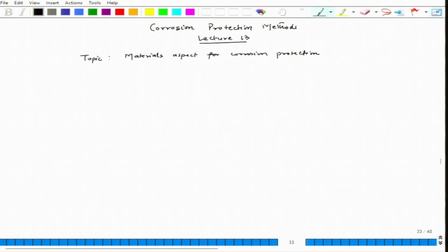One of the popular stainless steels is 304 stainless steel, used in applications like wash basins. In fact, it has more specific applications in biomaterials, where it is not 304, rather 304L, where L stands for low carbon. The carbon content is reduced from around 0.08 to 0.03 or 0.02, and we call it low carbon stainless steel. Again we have chromium about 18% and nickel about 8%, all in weight percent.